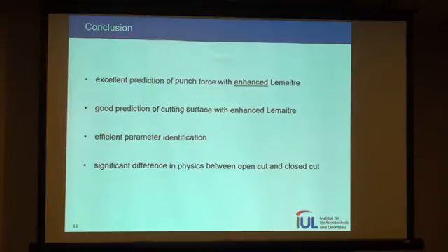So what can we say? We have found excellent prediction of the punch force with the enhanced Lemaitre model. We have achieved good prediction of the cutting surface with the enhanced Lemaitre model due to the consideration of compressive stresses. I've shown you an efficient parameter identification for the Lemaitre model, and we have found also that there are significant differences in the physics between shear cutting with an open and a closed cut.